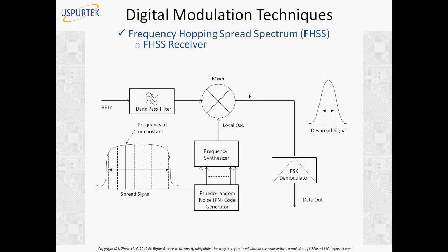But here, in the case of FHSS, because we are hopping from one frequency to another, suddenly changing frequency in the oscillator, like now it is 1 megahertz, next time it is 5 megahertz. So switching from one frequency to another, we do not maintain phase. The next frequency we choose may be starting from a different phase angle actually.